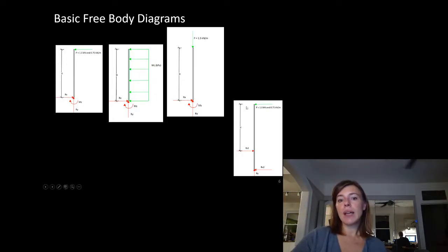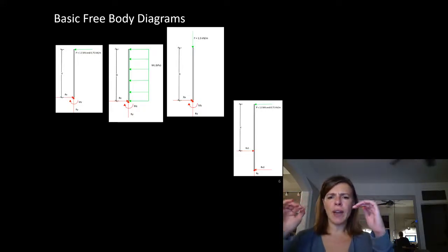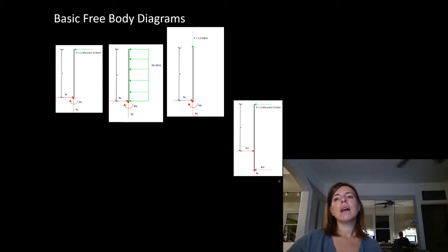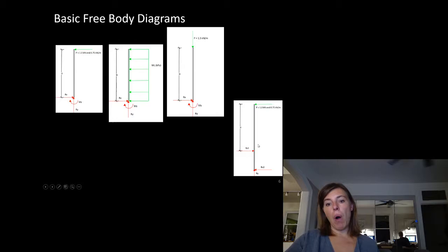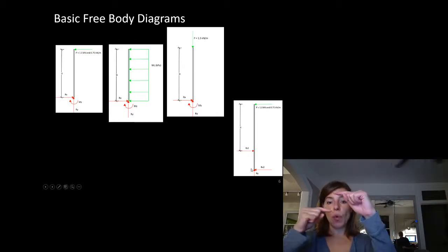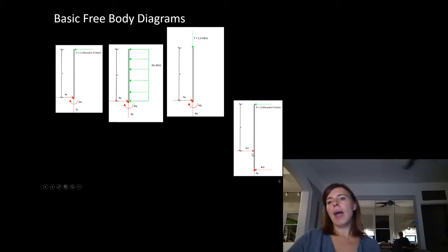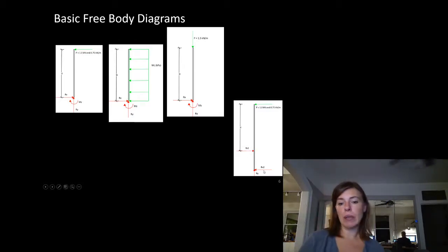So an applied load up here can be the equivalent of these 2 forces here to take out the rotation. And it's what we did all the time in beam analysis. So instead of a moment resistance, we're using a force couple to make sure we have resolved all 3 degrees of freedom. We have our y for up and down. We have 2 forces in x, and we have our x1 and our x2 to resolve the couple as well.